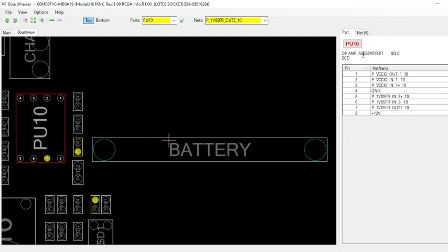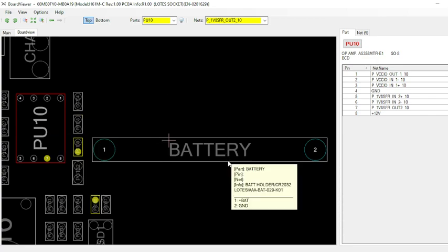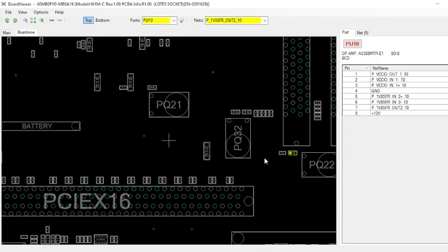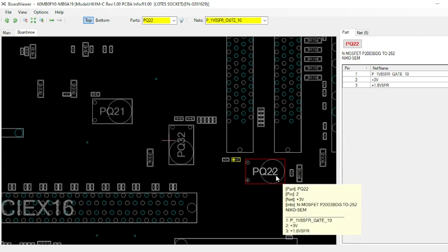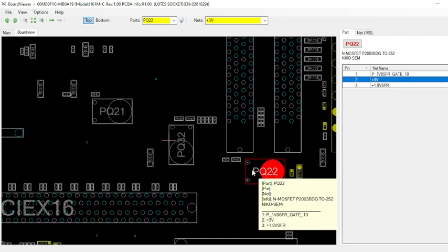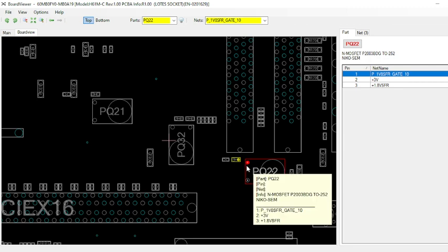Okay, as you can see, this is actually an op-amp. The letters may be LM or AS, so there is no kind of difference, but we have to check the number LM358, which is the operational amplifier that is going to control this 1.8 volt. What if this 3.3 is present and there is no gate supply?